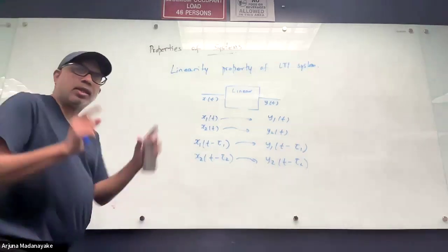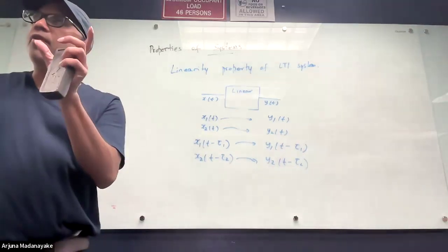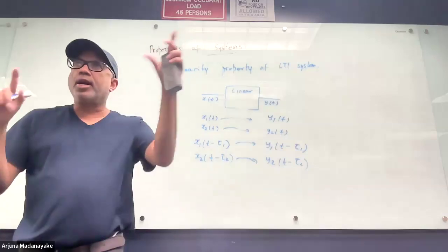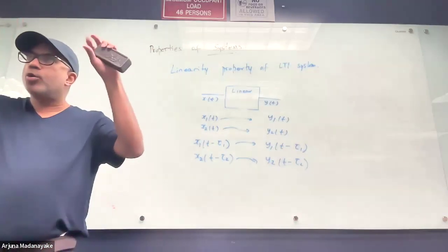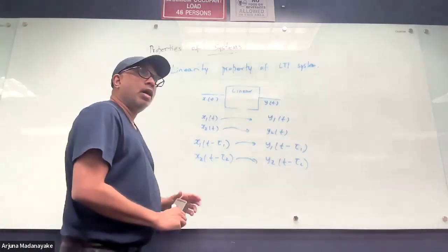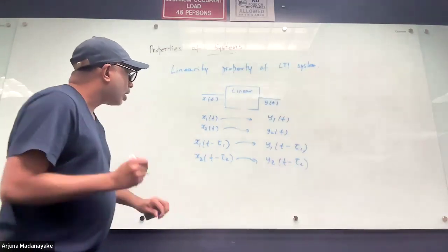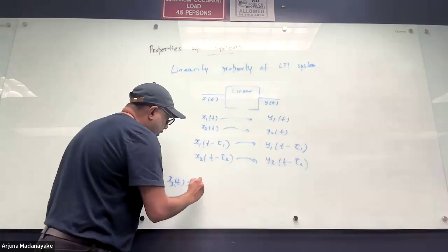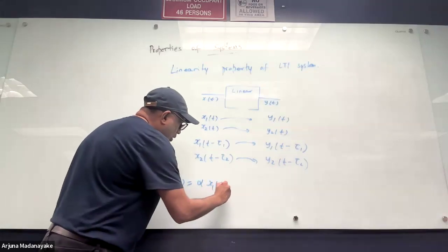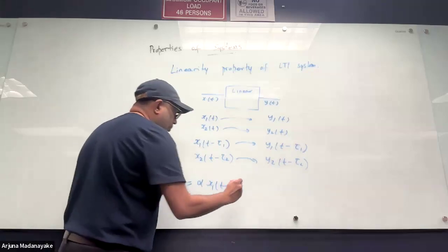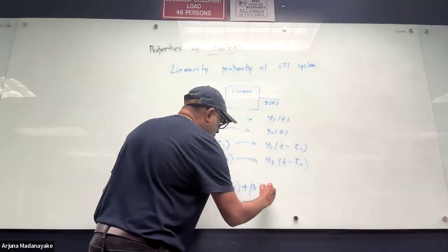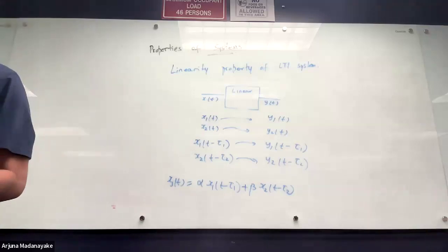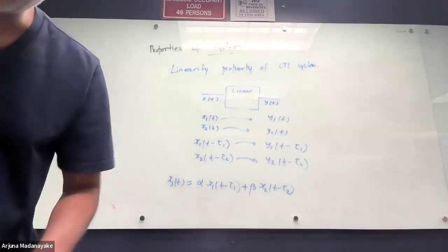Now, I take the combination of this linear time invariant part. The time invariant component corresponds to the time delays, tau1 and tau2. But earlier we looked at the amplitude variation in gain, alpha and beta, right? So I can now write, if my new input x3(t) is the scaled version alpha x1(t - tau1) plus beta x2(t - tau2), I can directly write down by inspection what the output is going to have to be.